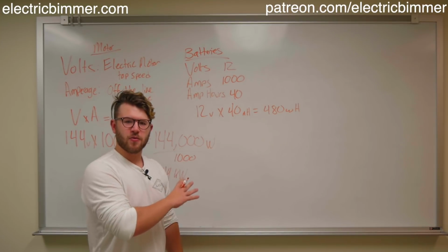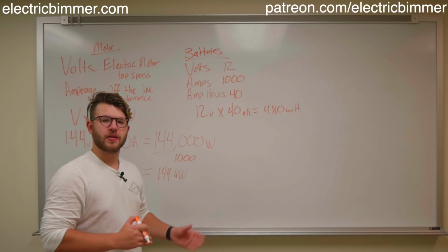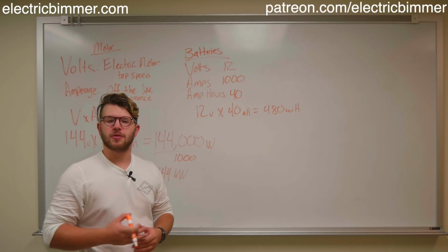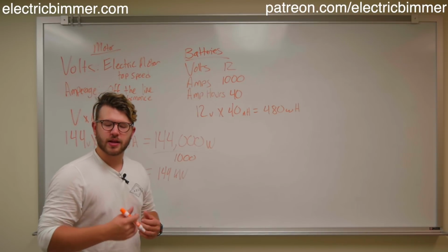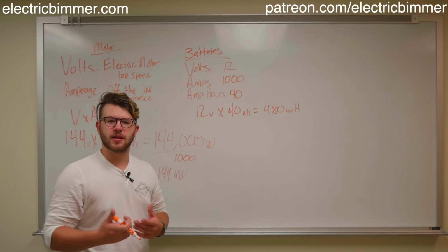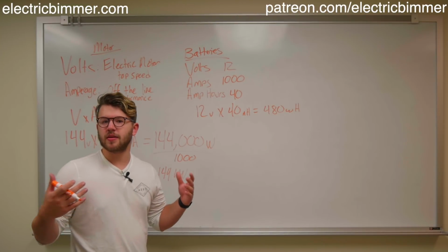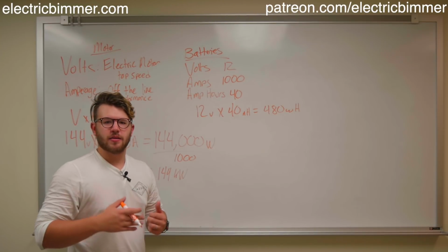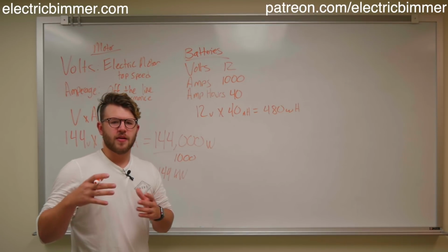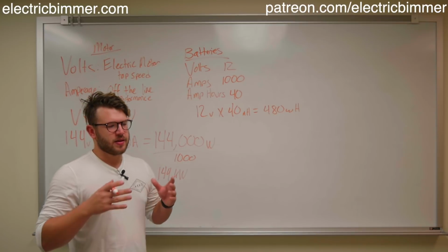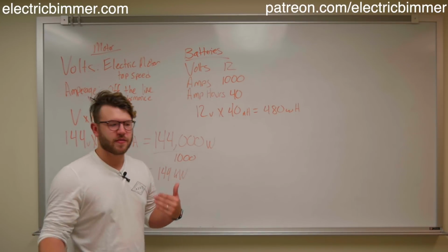Before I can make this full calculation, there's something else that we do need to calculate as well, and that is going to be how many watt hours our car takes to actually move. Now, I'm going to calculate kind of the worst case scenario number, so this is going to show you what is going to be kind of your minimum range with the vehicle that you're using. Likely you'll get further range, but this will kind of calculate for if you had the worst driving behavior with it. So this way, you will know what is the minimum that you're capable of.